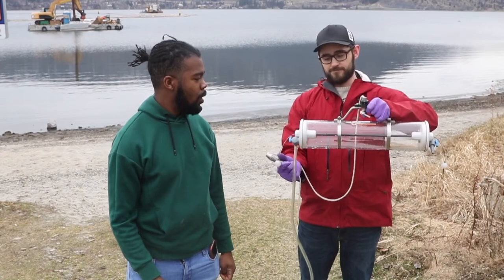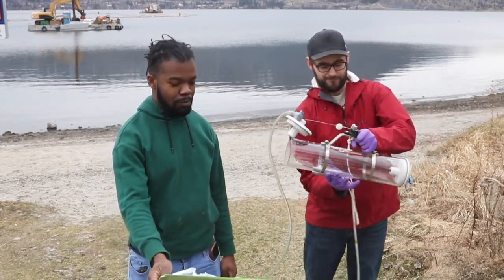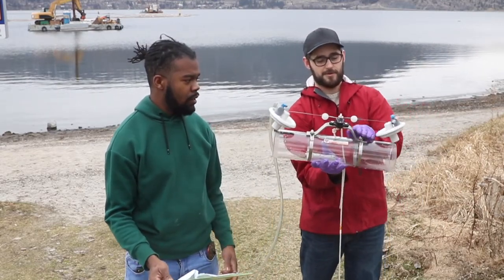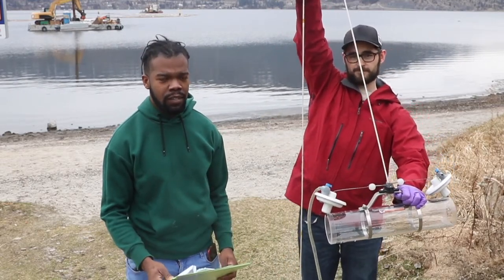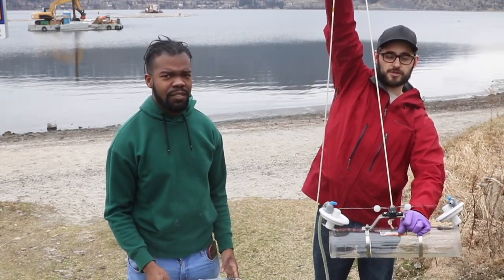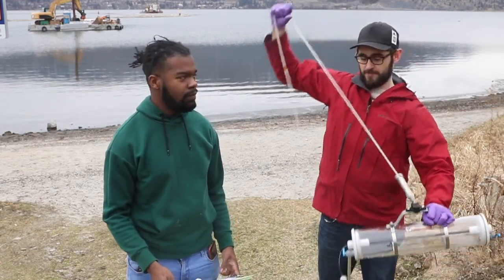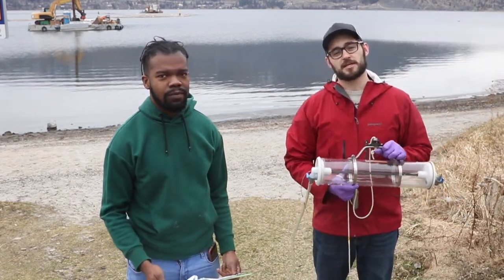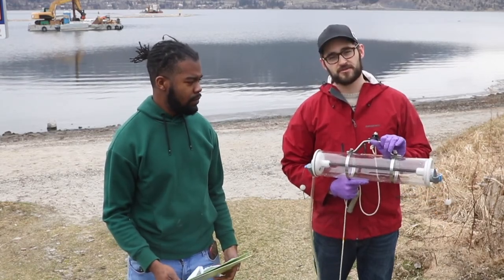First, we open the trigger. Like so. Then place it in the water at any required depth. Next, we will release the trigger to collect the sample. Next, we will return the sample to the surface of the water to collect the sample in our sampling bottle, which we will also drop 3 drops of the Lugol preservative in.